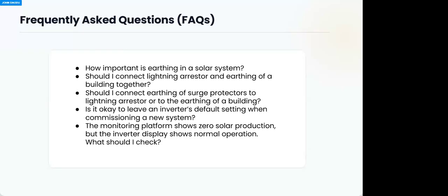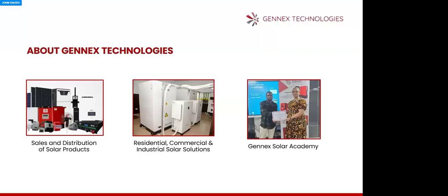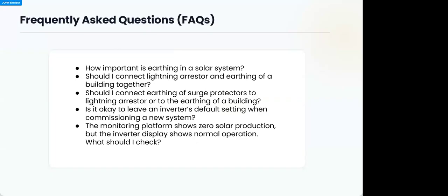Once that is achieved and you have a good earthing connected to the inverter, then the earthing coming from the lightning arrestor should go straight to the ground, because the advantage of the lightning arrestor is to capture the very high voltage spike in the space and drag it to the ground, to avoid a flash going into any cable, which can travel through the cable into the appliances. So the element up there will have attracted it and take it to ground.